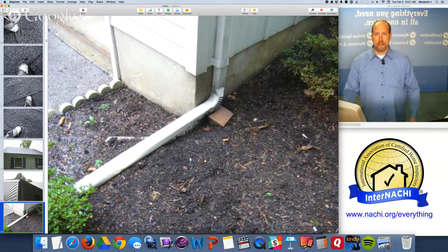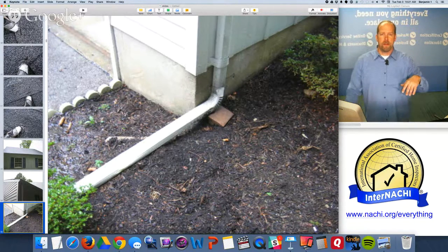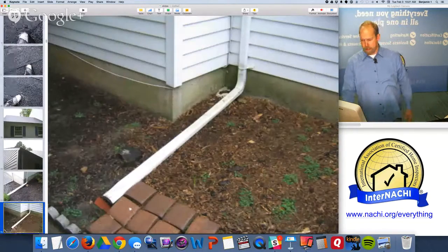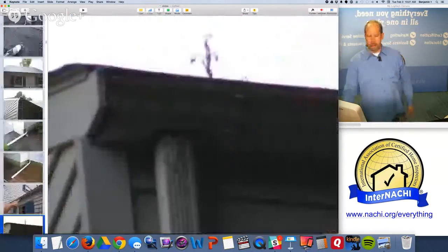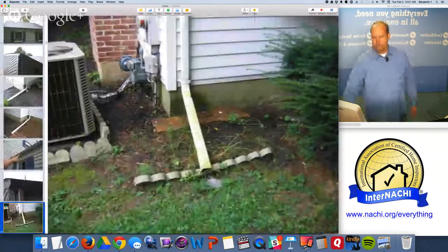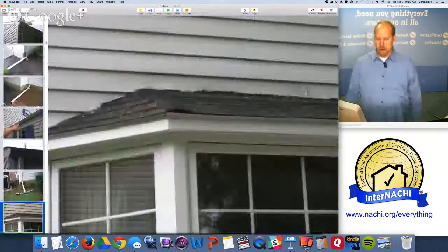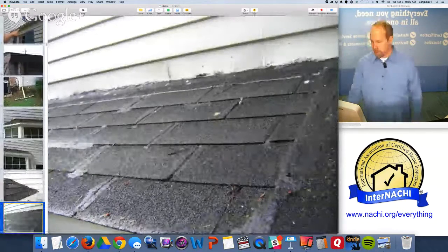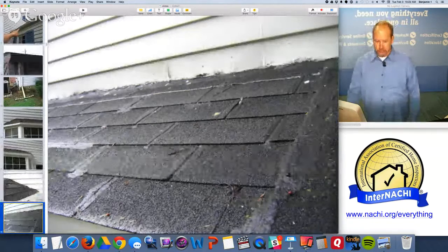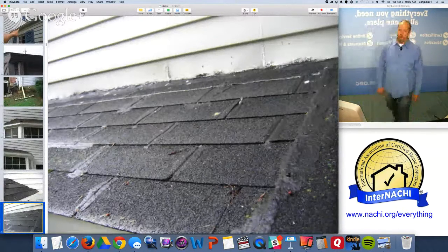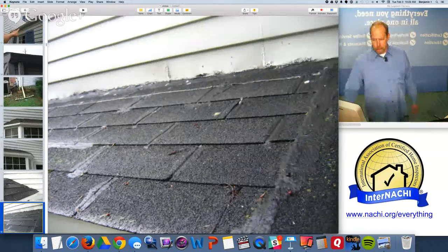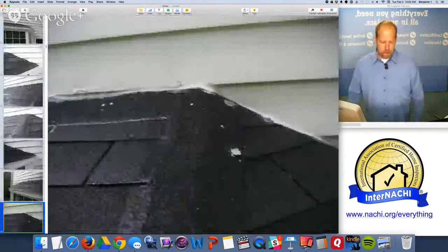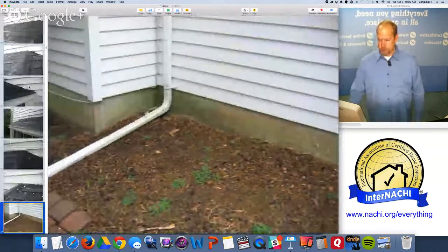And so I'm following the water flow from the roof to the gutters, downspout to the grating. I'm checking out anything that is missing, like a missing gutter strap, downspouts that are not diverting water far enough away, little bay windows that have their own roof problems. This one is definitely leaking. Almost every tab has been sealed up. Not sure what's going on here. It's probably a flashing problem. They just don't know that it is that, and so they just seal up every shingle.